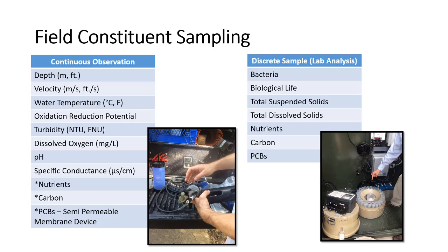A lot of times these sondes, and actually the acoustic Dopplers, will also measure water temperature. Do you guys remember the pressure transducers, the sensor that's mounted on the bottom and uses hydrostatics to measure depth? Pressure and temperature of water co-vary, so the pressure is affected by the temperature. A lot of times those pressure transducers will also measure temperature, so that if the temperature fluctuations are dramatic enough in the channel, it can make those adjustments on the fly. Okay. So temperature is a fairly straightforward one to measure